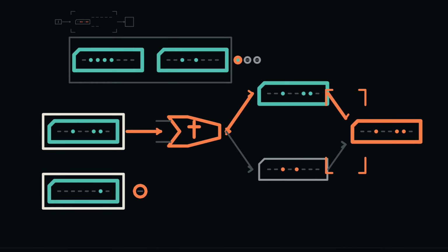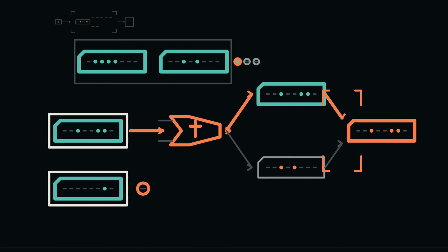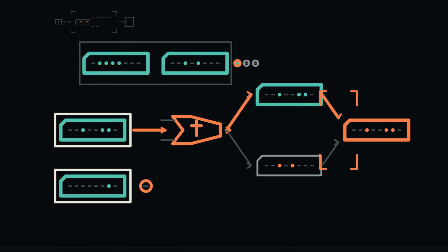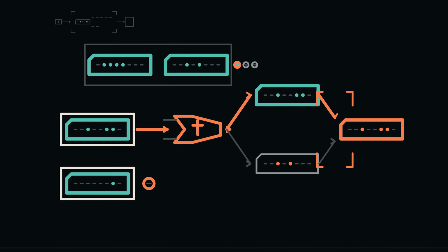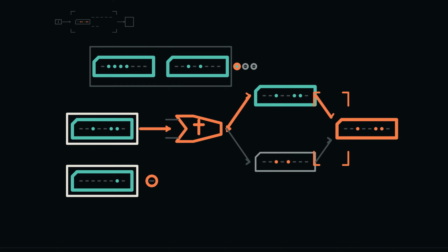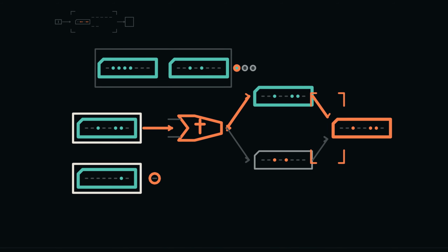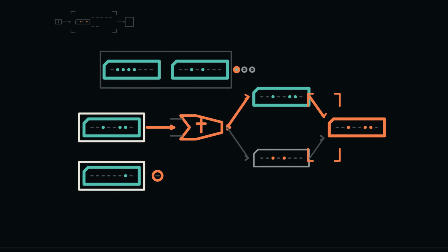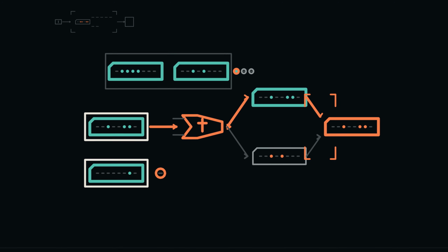Fetch the branch at address 24. During its 2-byte fetch, PC advances through 25 and then to 26. Decode reveals branch if 0, target 28. 0 is currently clear. Predict the execute edge. The branch condition is false, so PC preserves the already advanced value 26. It does not add 2 again, and it does not load 28. The trace records branch not taken. The next fetch therefore begins at 26, where the unconditional jump is stored. Not taken means ordinary sequence survives. It is still an explicit branch outcome.